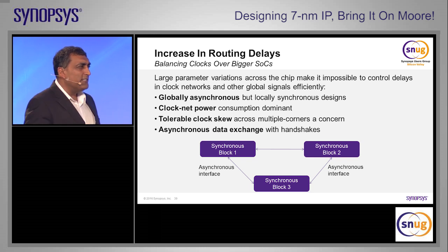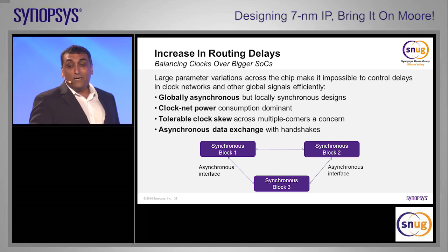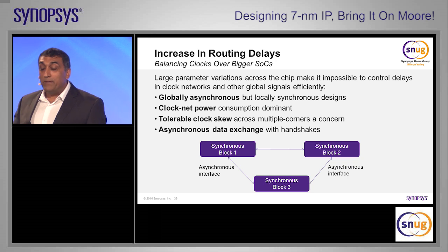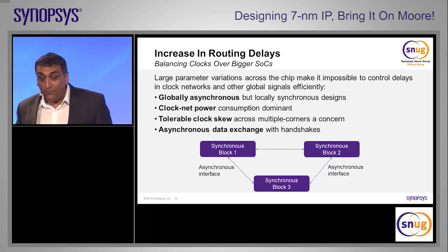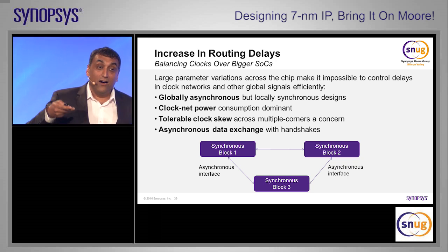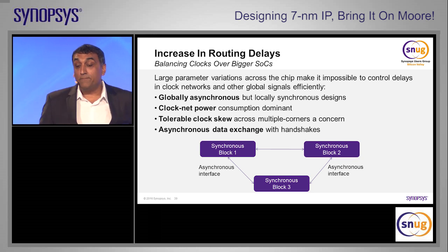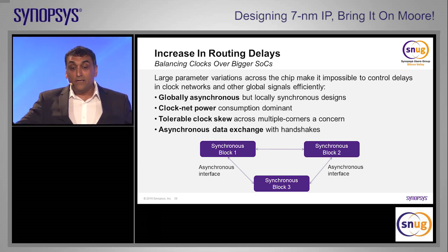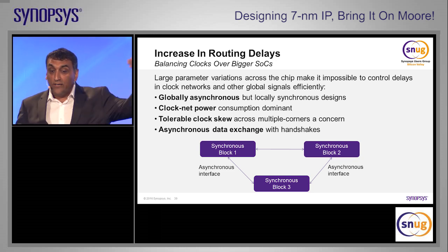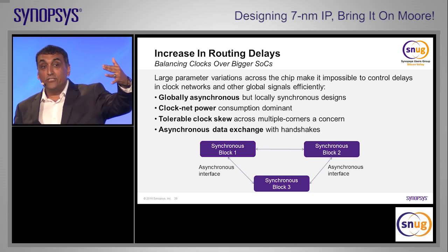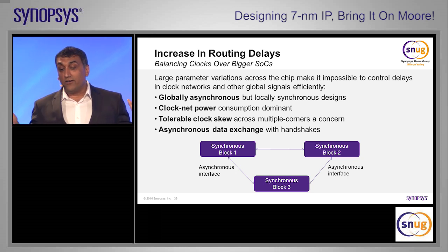So this is a technology that's 20, 25 years old, but GALS is now being implemented again, both at the SoC level and at the large IP level. So when we're developing our big, more complex controllers with a connection to an AMBA bridge, for example, that's a lot of gate count.